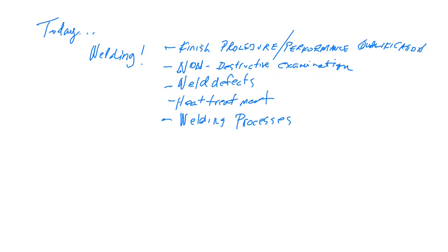And I hope that we'll get finished heat treatment today, which you're going to find is all about metallurgy. Back when we were covering metallurgy, we looked at different unit cell structures. We had ferrite, pearlite, austenite. Ferrite and pearlite were body-centered cubic, and austenite is face-centered cubic. And then we had this thing called martensite, which was body-centered tetragonal, and we learned that iron could change its unit cell structure. It depends upon its temperature and also on its rate of cooling. And that's where all of this heat treatment stuff comes in.